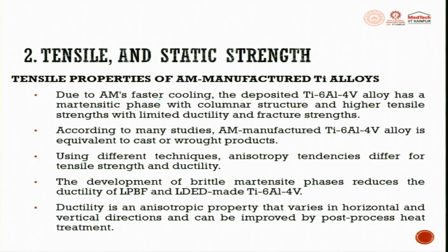Due to AM's fast cooling, the deposited Ti6Al4V alloy has a martensitic phase with columnar structure and higher tensile strength, with limited ductility and fracture strength. All these lecture slides have been extracted from various research papers. So, that is why you see some of the things are abstract, but all these things you will be able to appreciate when you parallelly go through the